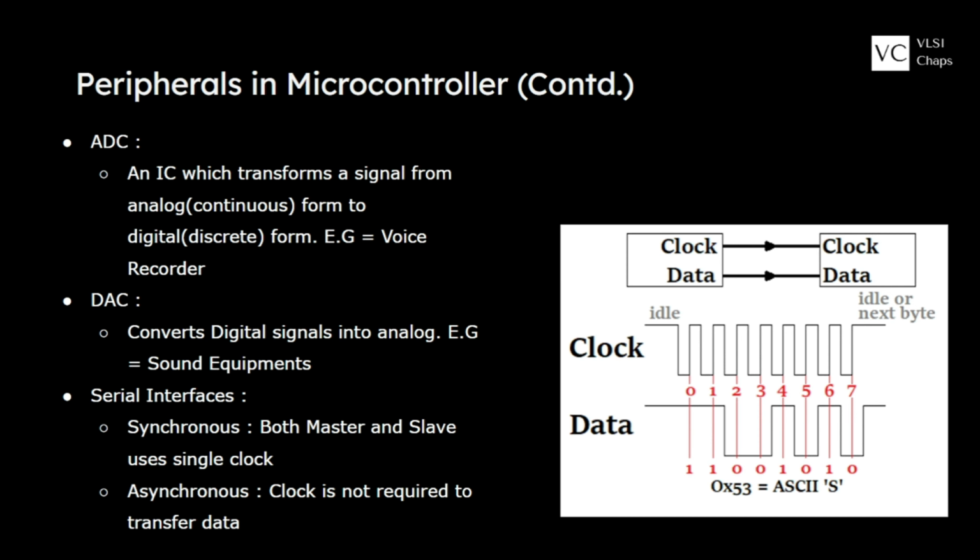If we talk about the asynchronous, then there is not any clock functionality at all. The transmitter will transmit the data in terms of bits or chunks of the bits. So whatever the transmitted data is there, in order to receive those data, there should be some functionality or mechanism by which receiver will be able to know that okay, this is the start of the bit of this whole chunk, this is the stop bit of that whole chunk, and this is how I'm getting this whole frame.